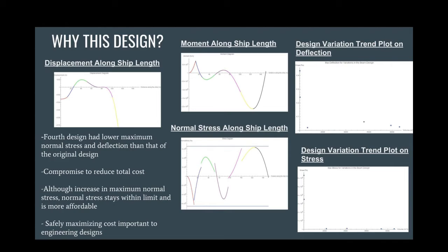So as you can see from our trend plots, reducing the dimensions represented in volume for the girder ended up in a higher shear stress. We ended up calculating that we could go up to 0.6 times the yield stress of the Kevlar epoxy. We calculated that number, and that is what our moment of inertia is for the girder we currently have.